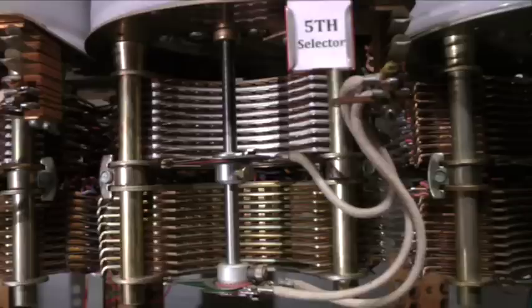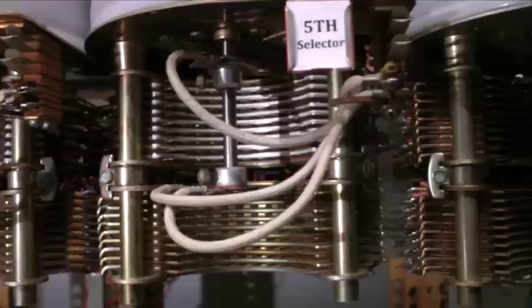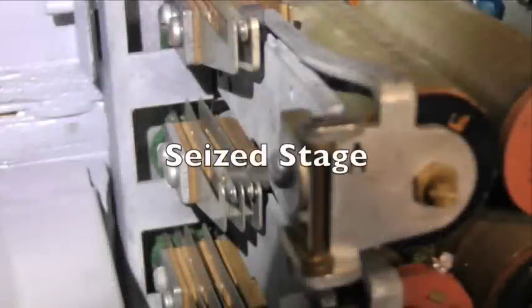As the dial returns, the 5th selector shaft steps vertically to the 10th level. It immediately begins rotary hunting for an idle connector. It finds an idle connector on the 10th set of bank terminals, and its wipers are brought to rest on these terminals. The 5th selector then extends the calling station's tip and ring leads through to the connector. At the connector, the A relay windings are bridged across the incoming tip and ring leads. The loop through the calling telephone set operates the A relay.